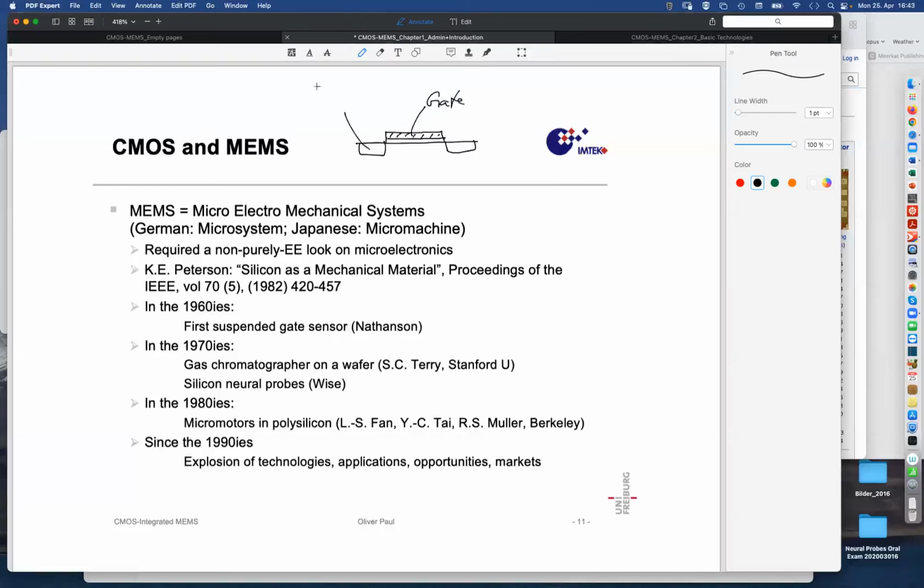And then here we have the so-called source, and here the drain. They all are contacted. So here there's some contact, and there are some insulating layers also. And this below here is silicon. So it could be, let's say, P silicon, then this is N silicon, and then here we have this little channel.